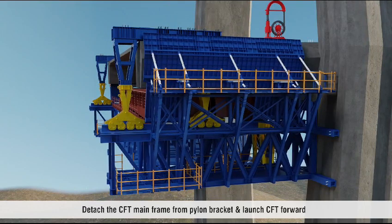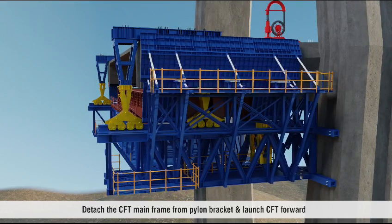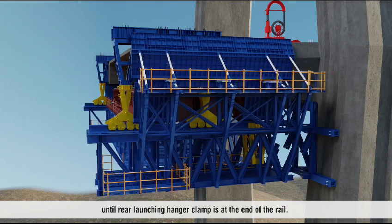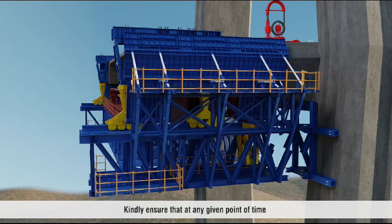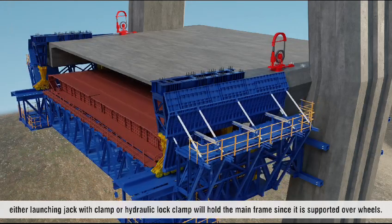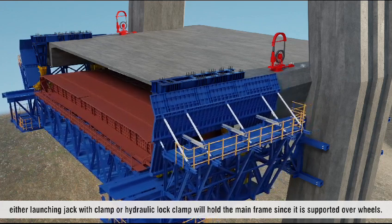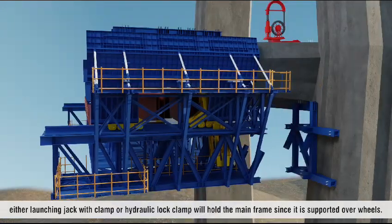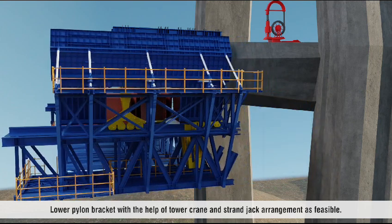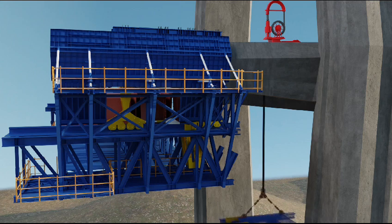Detach the CFT main frame from pylon bracket and launch CFT forward until rear launching hanger clamp is at the end of the rail. Kindly ensure that at any given point of time, either launching jack with clamp or hydraulic lock clamp will hold the main frame since it is supported over wheels. Lower pylon bracket with the help of tower crane and strand jack arrangement as feasible.